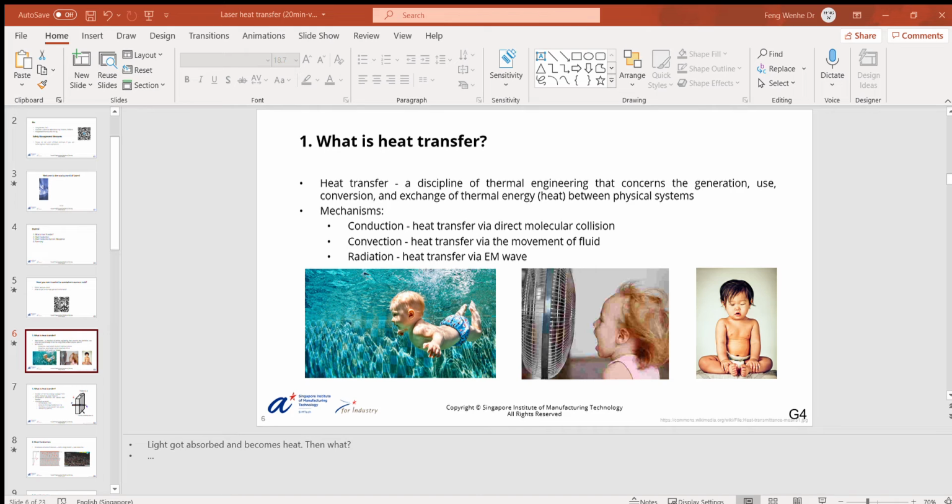So this equation is known as the unsteady state 1D heat conduction equation, and you can also shrink it into a heat equation by dividing everything by the thermal conductivity. Now you have another derived physical definition known as the thermal diffusivity. The unit is meters squared per second. It describes the thermal conductivity relative to the density and specific heat capacity of this material.